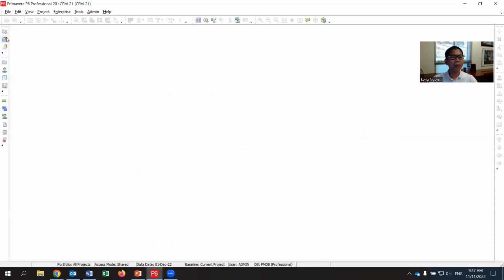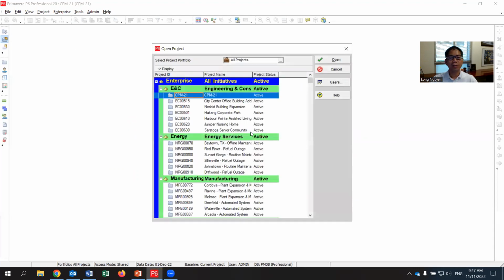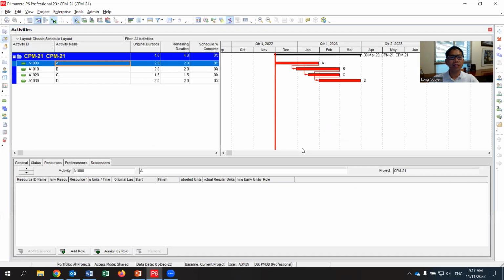In a previous video, we created a project already, and that's the same as your deliverable number one. You already developed a schedule for the project. So let me open that project here, CPM 21, and now the activities that we already have. Now we want to integrate the costs or any type of resources in this schedule. So how can we do that? First, we need to define resources.